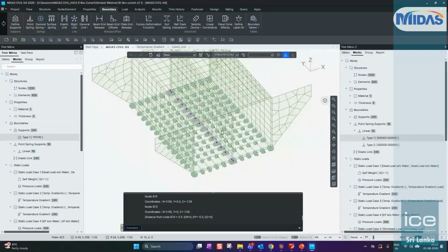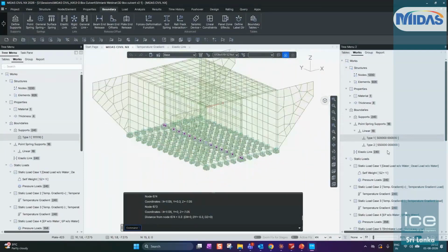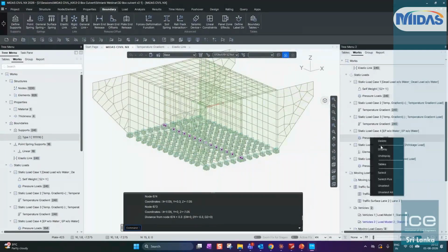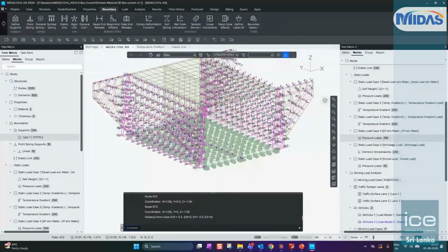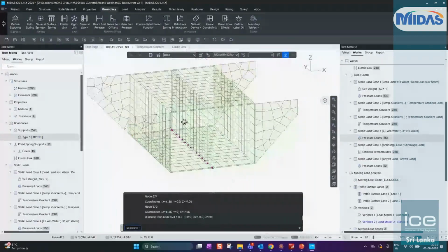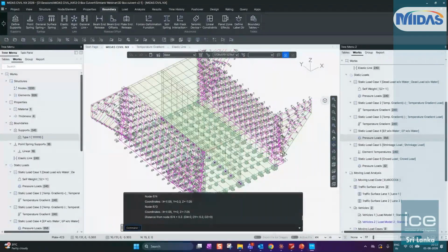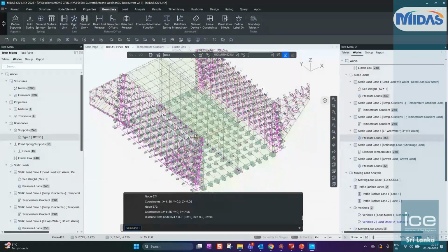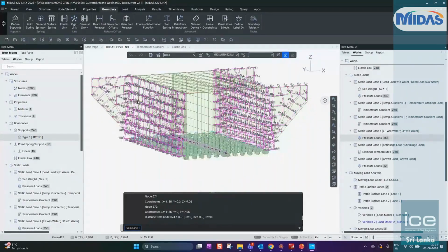Okay, because we have assigned, let me switch on the loads, right? We have assigned the lateral load to this, because this is a symmetrical structure and the loading is symmetric as well, so the net value will be 0. But if you have some difference between the soil levels on the two sides, because ideally the soil will not be equal in all cases. If you have a sloping highway, then you might see different values of soil height on the two sides, right?